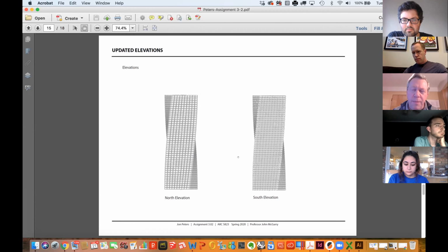You could, help me out with this, John, this is what Leland showed with their design study in Beijing, is that actual daylight quantity as opposed to sunlight access produced a different orientation of panels, because the daylight down there in the street is quite low as opposed to higher up in the sky. So you could artificially create, or realistically create, a top to bottom gradient, as well as a twist gradient like this, based on anything that could measure the ambient daylight within your model. So that would be another way.